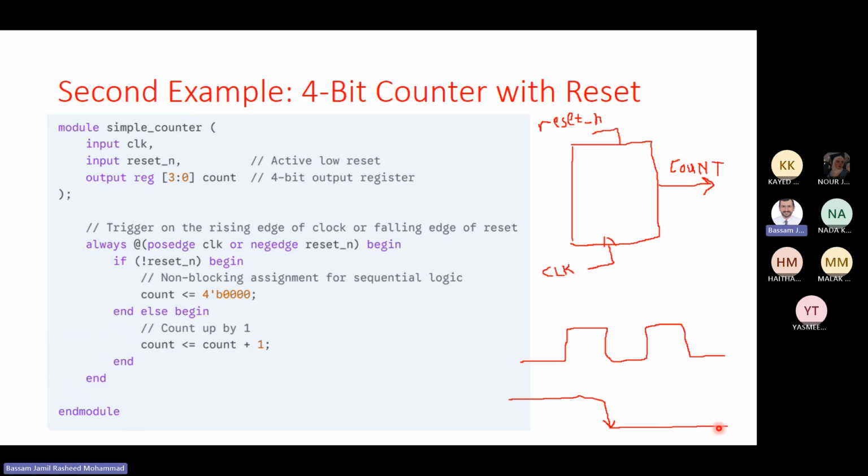Now, when you make the values of all the flip-flops zeros, this is a known state. Okay, so when we power up, we need to do this. Reset must go down, right, and inform the hardware, especially the control circuits and the flip-flops, to be in a known state. All right, which means that if I press reset to 0, from high to low, my counter has to go to a known state, and typically 0 0, which means we reset it to 0 0.